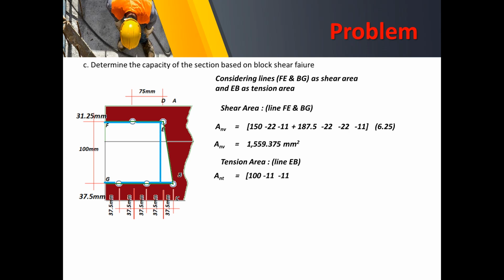Of course, we take into account the D prime formula, or S squared all over 4G. Now let us correct that expression. This is S squared all over 4G to account for the pitch distance. So again, we multiply that one by the thickness. Hence, we arrive at 509.47 square millimeters.